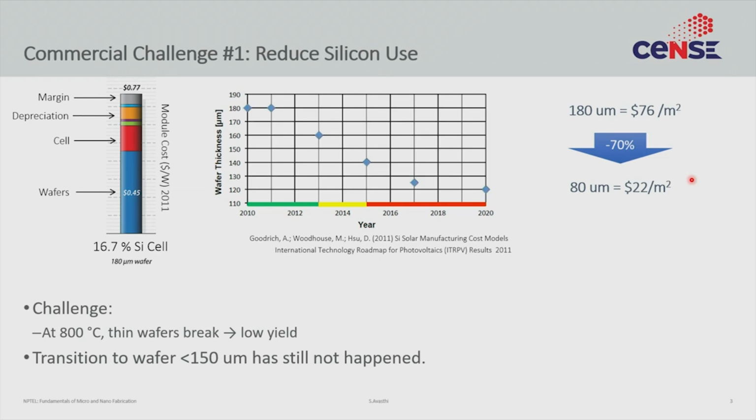But that was not an option for solar. So the solar industry really tried to reduce the amount of silicon, and the only way they could do that was by reducing the thickness. So they came to this magic number of around 180 microns for a 6-inch cell, which is still significantly thinner than what Intel is using, but any thinner and they realized that they break too many wafers, and because the yield is not there, they couldn't go any further. So the moral of the story is that cost is one thing, but yield is extremely important.